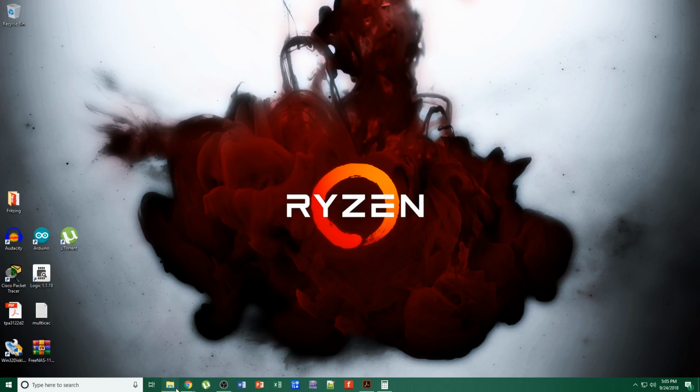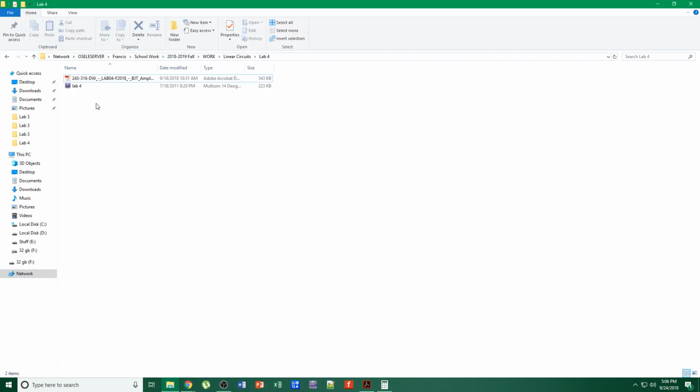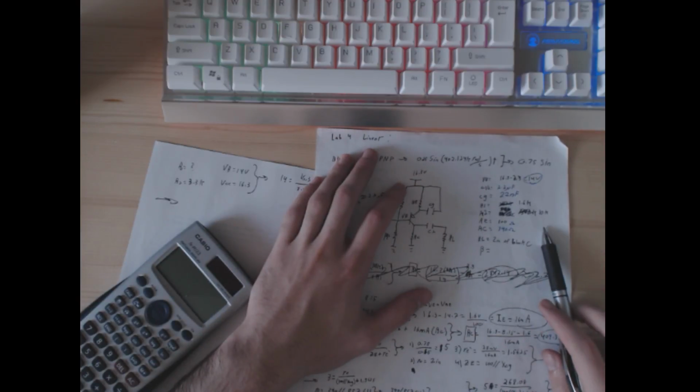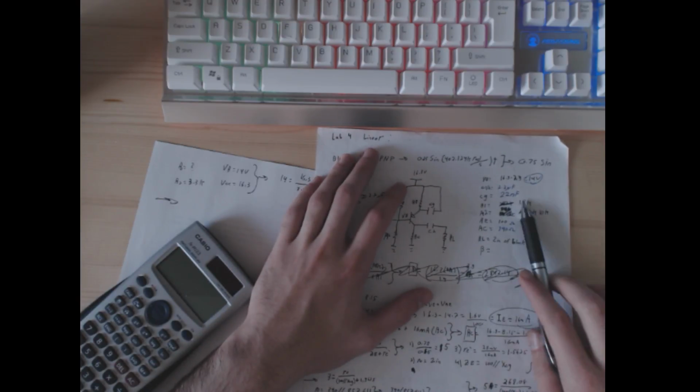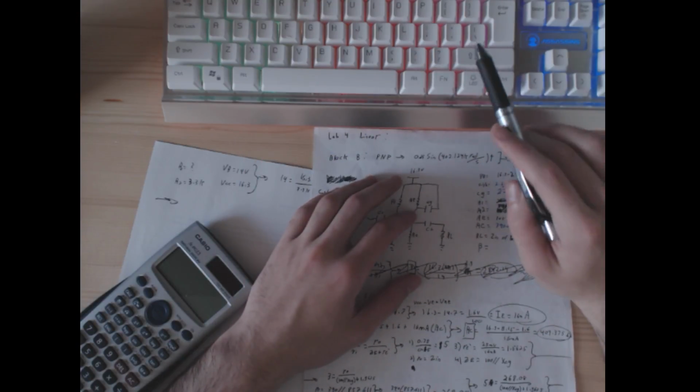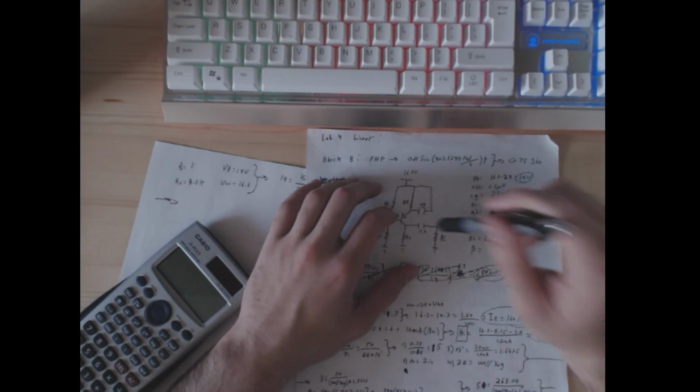So that's pretty much the multisim of that. This is 10K. This becomes a 1.6K, which I changed over here. From the calculations, I just changed those two numbers. Everything else should be fine. So the best way would be now to test it.